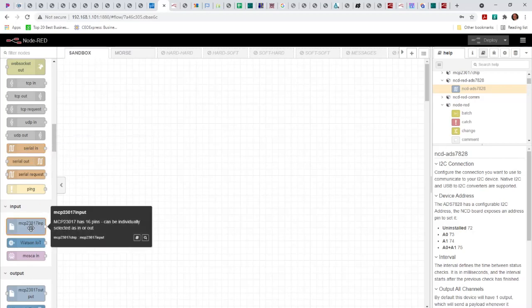Now here's another example of an input for a specific chip. This is a port expander for I2C. You can send I2C signals over the I2C bus with just a serial clock and a serial data pin, and then provide voltage and ground to the chip. And it will actually send that signal, that pin out, that bit. It'll pull a bit high or low on any one of 16 pins. So one I2C bus of 2 wires can control digital inputs and outputs of up to 16 pins, which is a very cool chip to be able to let you expand your I2C part.